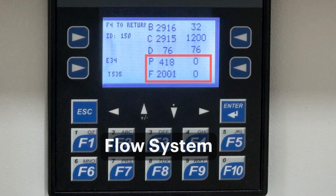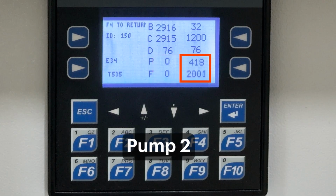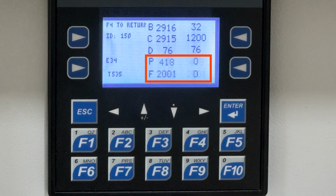The bottom 2 rows labeled P and F apply to the flow system. If the values are populated in the middle of the display, pump 1 is operating and pump 2 is off. If the values are populated in the right column, pump 2 is operating and pump 1 is off. The software will automatically cycle the operating pump between pump 1 and pump 2 after each tape advance.